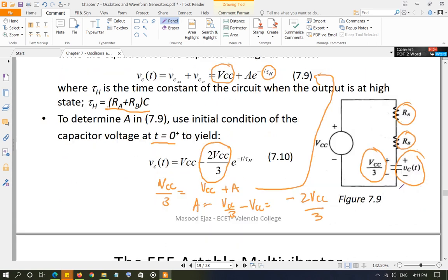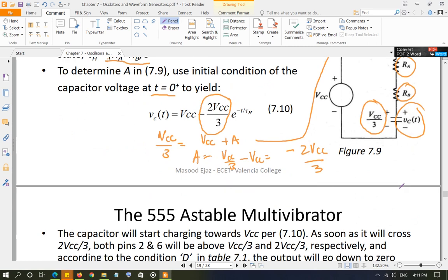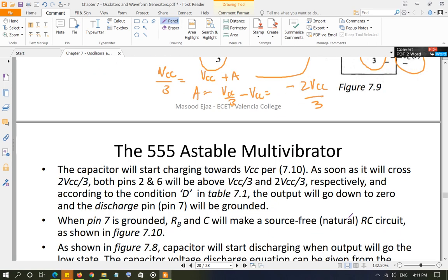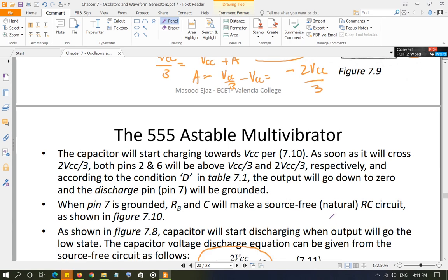of the op-amp astable multivibrator. In that circuit, our time constant was the same when the capacitor was charging and discharging, so it was a square wave. In this case it's not a square wave, because the time constant is longer when it is charging and shorter when it is discharging. So basically, the duty cycle is how long the waveform is at its highest state divided by the total time period. So the duty cycle is going to be greater than 50% in this case.